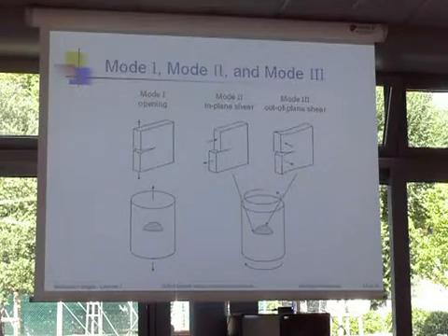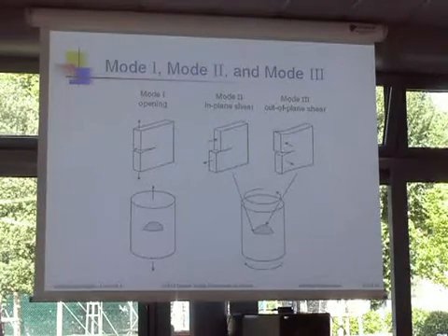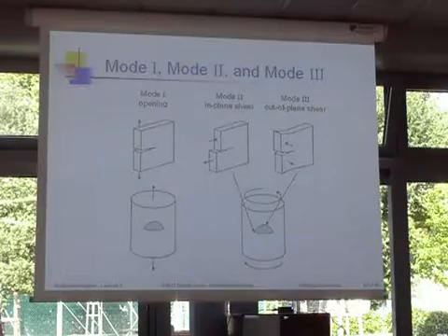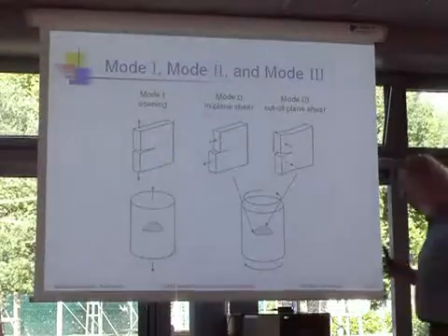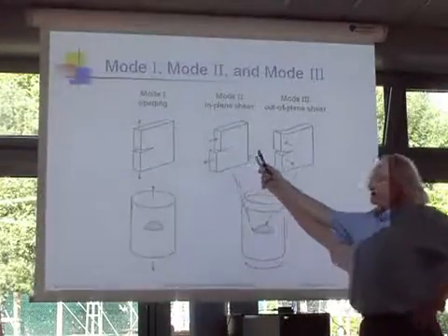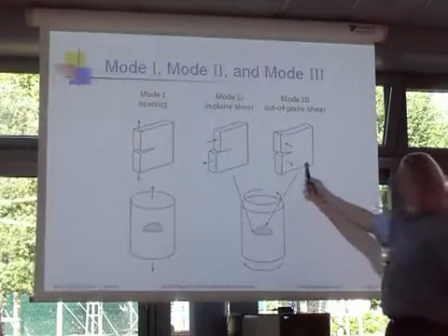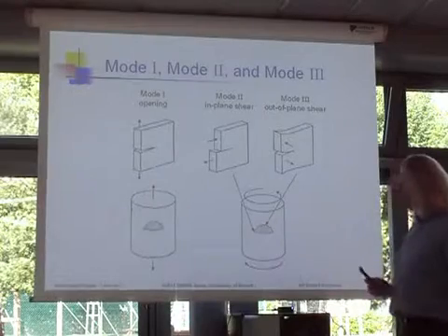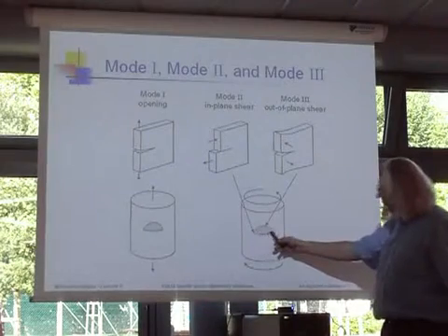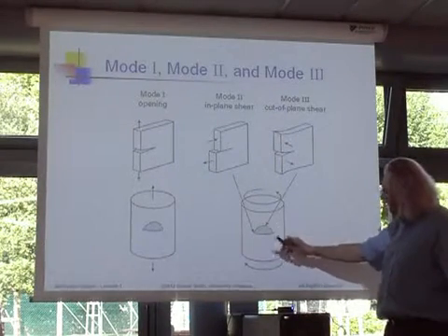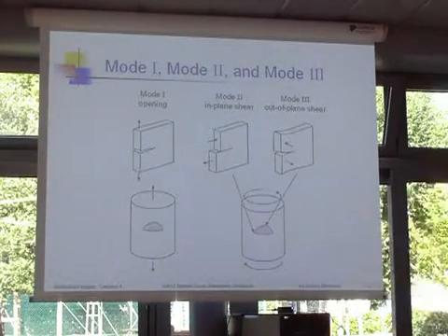So far I've talked about these macroscopic cracks growing, and I've really talked about mode 1 opening, and of course we can have these different modes of loading, 1, 2, or 3. Of course the opening mode 1, you can have mode 2 loading in a plate, but it's difficult to get. You can have mode 3 loading in a plate, which is tearing, which is pretty easy to get. It's also easy to get modes 2 and 3 loading in torsion of a cylinder, because if I have a thumbnail crack in the cylinder, on the surface that you see is always loaded in mode 3 and mode 2, and at the bottom of the crack is always loaded in mode 3.